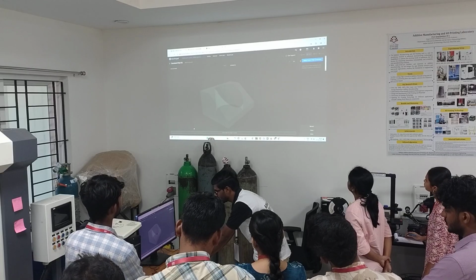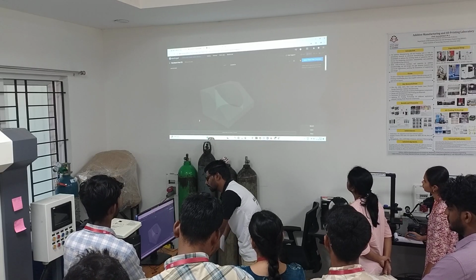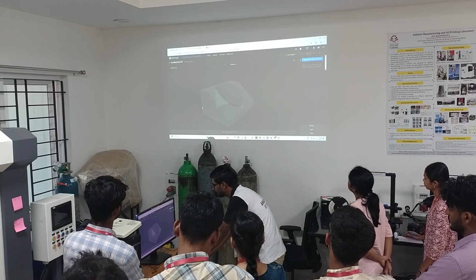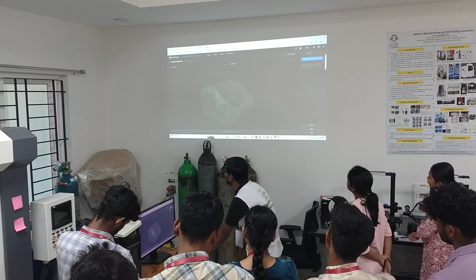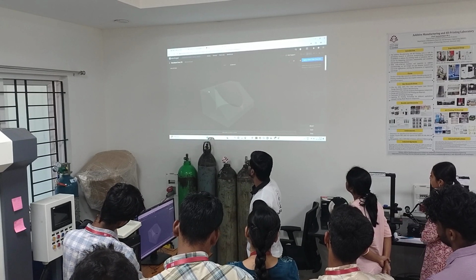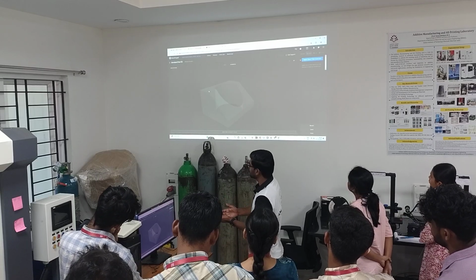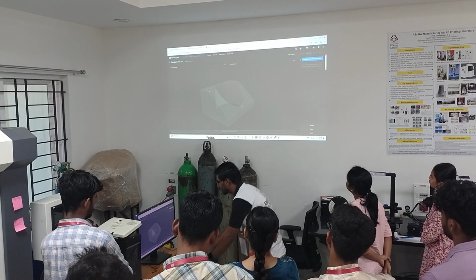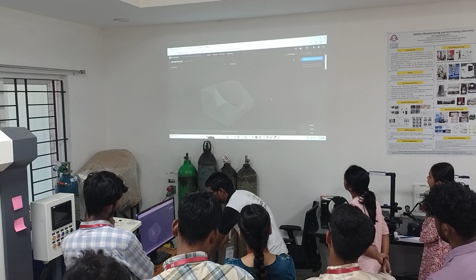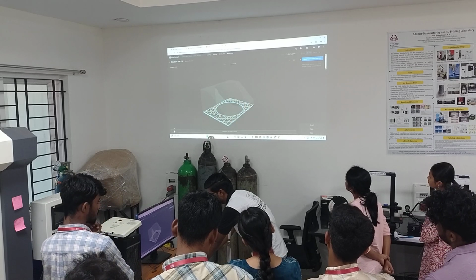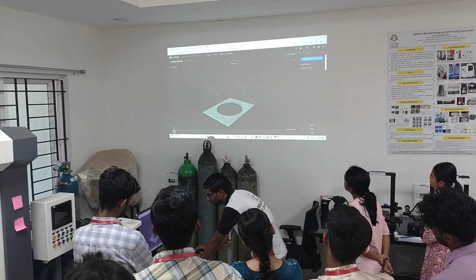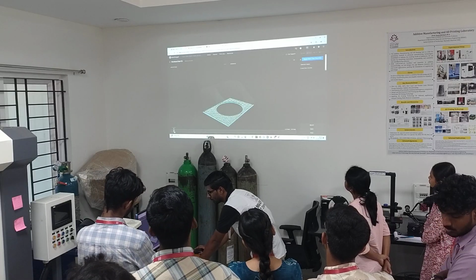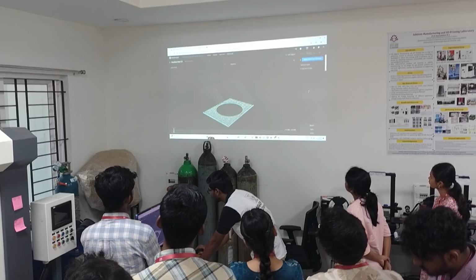So there are some restrictions. From the side wall, and from the bottom as well as the top, there must be a gap of at least 2 layers of the plastic or the matrix. Only after that can we place the fiber material. So let me start from the fourth to fifth layer. We have 2 layers of carbon fiber I'm going to add.